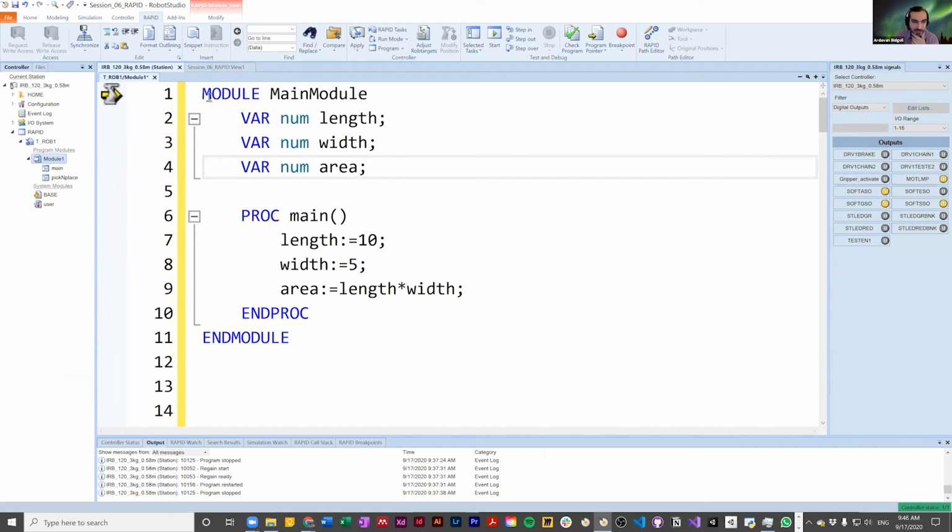As you can see here, it starts with something called a keyword. And keywords are in RobotStudio dark blue, which means that this word is being saved and preserved by this programming language, and it can only be used in this capacity to define the beginning of a module. So this is a mandatory part. For any type of code that you write in Rapid language in this class, you need to start with this word, MODULE, and then say something after it.